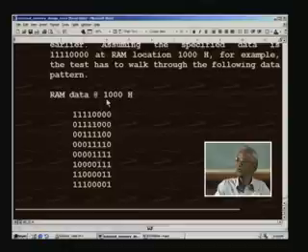So, what we need to do is, the user will have to specify what data is to be written at what location. This location address as well as data will be furnished by the user, and you have to take that as an input for this test, conduct this test and then report whether it is a pass or fail. And what we do here is, suppose the user has given this as the data, we write this data into this RAM location, and check back to make sure that it is the same data.